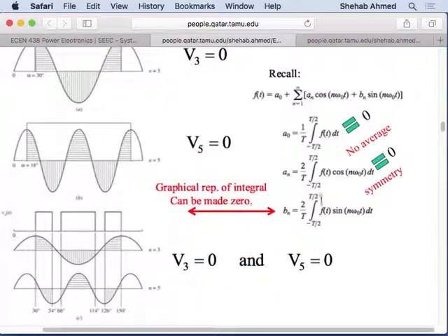An in this equation is the integration of the waveform multiplied by cosine n omega t, and then this is the bn values. We're dealing with AC waveforms, so these waveforms don't have an average value, and if we choose a reference properly, then we can use odd symmetry, even symmetry, and get rid of the ANs as well. We can write any waveform in terms of a set of cosines or sines if I have the pleasure of choosing where my reference is.